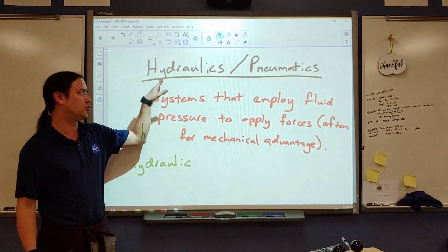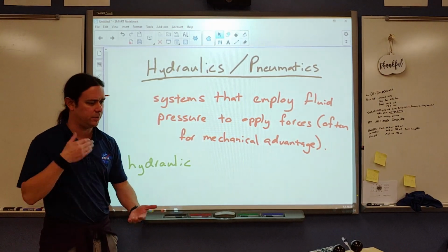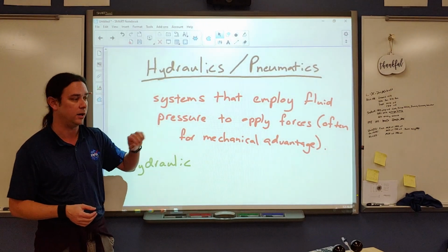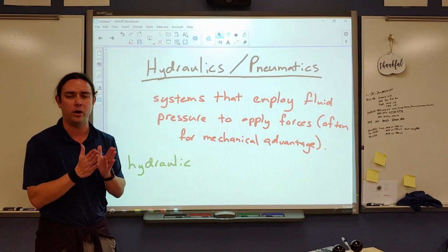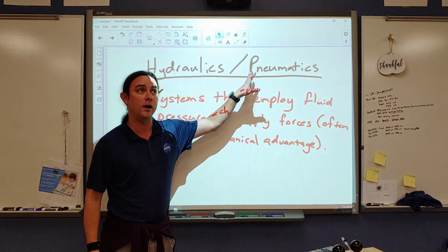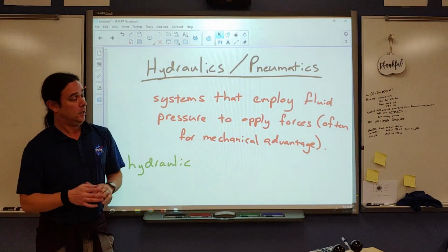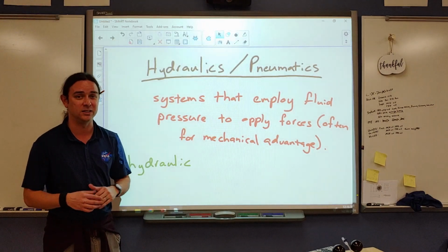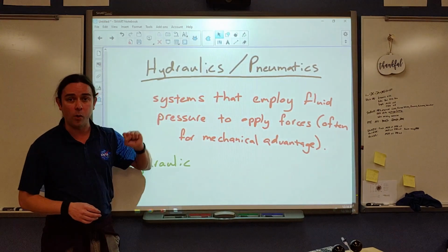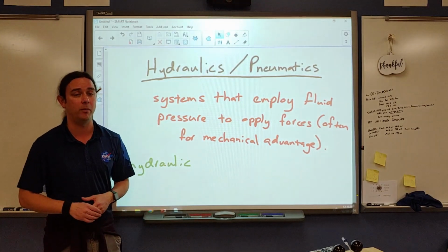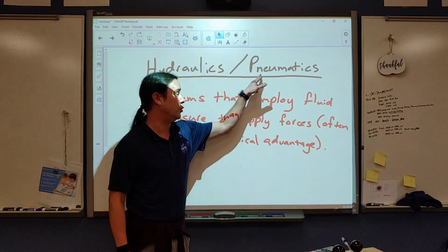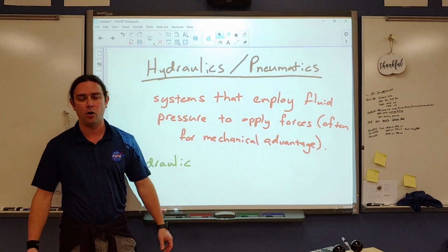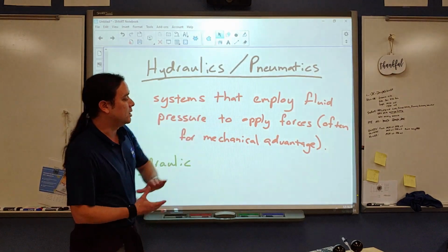They have upsides and downsides. Hydraulics are usually ones that are much more solid on being able to, first off, deliver a very predictable amount of force because of the incompressibility on it. And they can kind of get supercharged because you don't have to worry about compressibility. Pneumatics is often a cheaper, lighter, and cleaner, for want of a better term, way of approaching it. So in robotics, we were never allowed to have hydraulics on the robots because if you spring a leak on that, you end up with that liquid, the hydraulic fluid, getting everywhere, and it's a terrible mess to clean up. If you take a hard hit and you have your pneumatic system punctured, however, you leak some extra air into the air or whatever. Like, it's still a pain, but